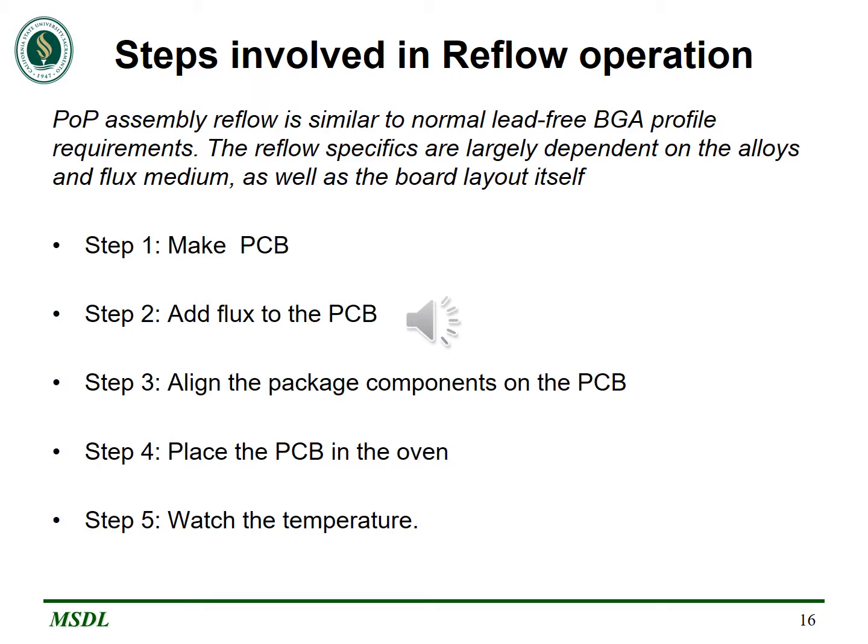It is very important to design the PCB board with pads for each and every ball along the silk screen outline to make it easy to align the components. The next step is applying flux over the board prior to doing the reflow process. If flux is not added, then oxide over the top of the pads will create some slightly squeezed balls which will not be connected to the PCB board. Next, all the components, that is packages, should be aligned properly over the PCB board.